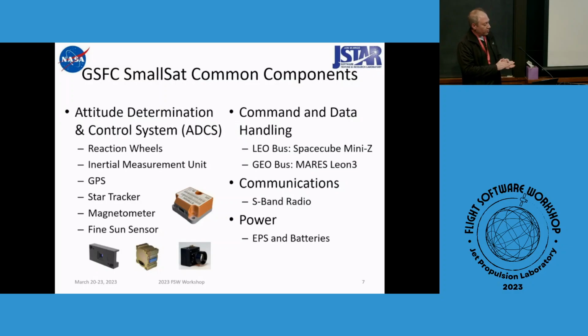This slide shows our effort to genericize and make the components integrated into NOS3. We have attitude determination control system components such as reaction wheels, GPS, star tracker, magnetometer. On the CNDH side, command and data handling, we have the Space Cube Mini Z and the Mary's Leon 3. For communications, we have an S-band radio model. And for power, we have a generic EPS and battery model.